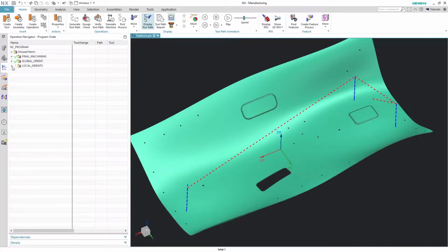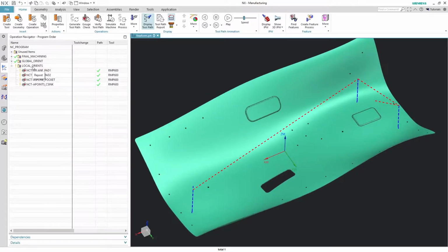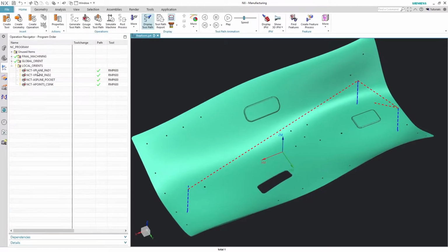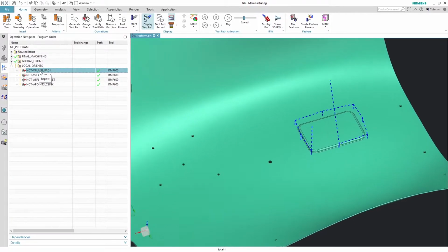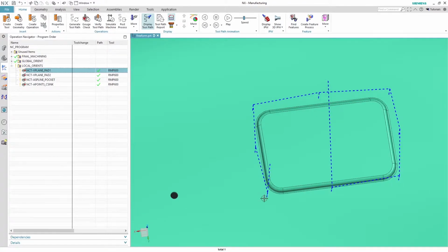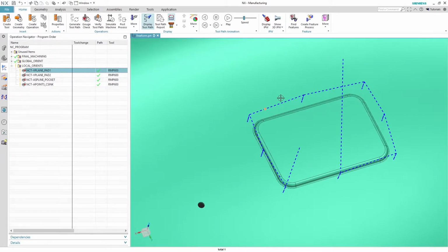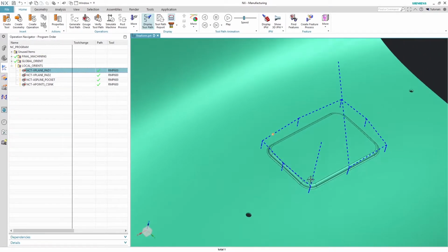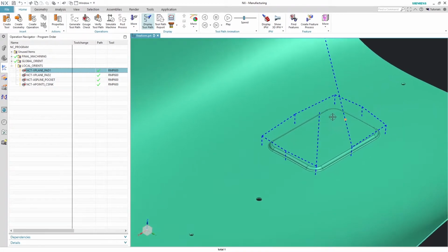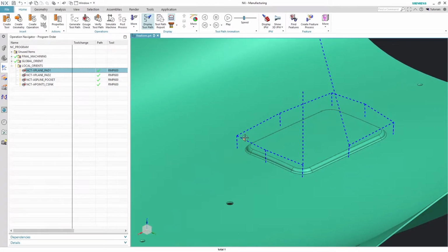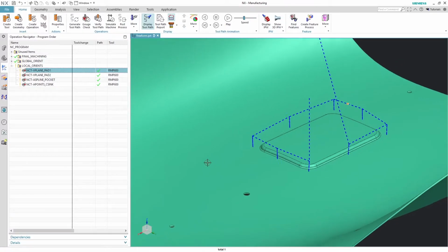The next thing that we do is apply what we call a local orient. It's an orient that's applied to a specific area in the cut program. And we're going to use several features in this example. The first is something called a virtual plane. We probe around the periphery of the pad, and we can use a minimum of 3 points. We can use as many points around the outside of that pad, and that will adjust that pad surface to match the actual location of the part surface on the machine.